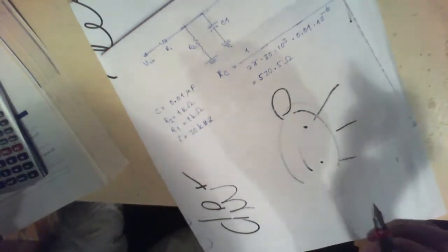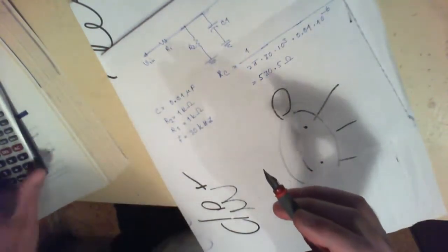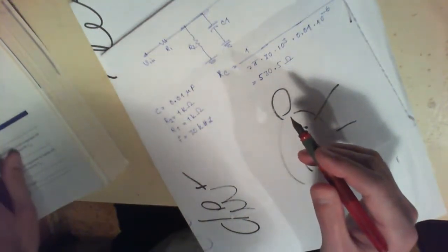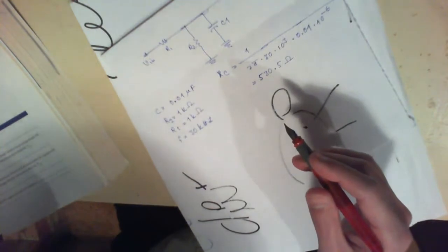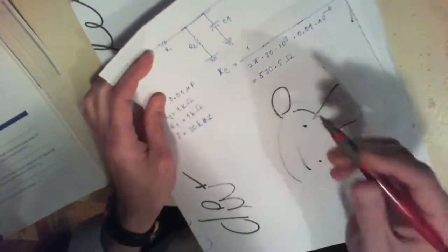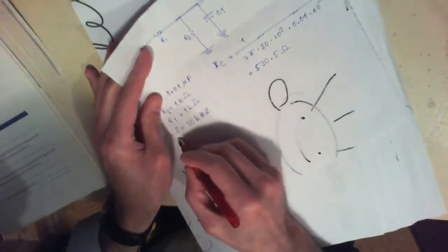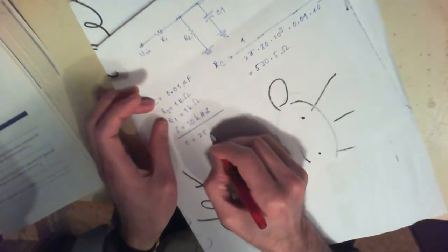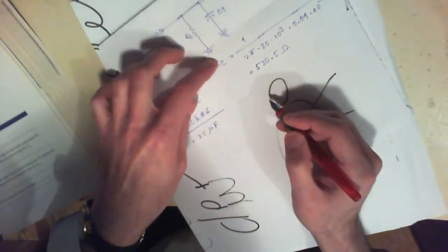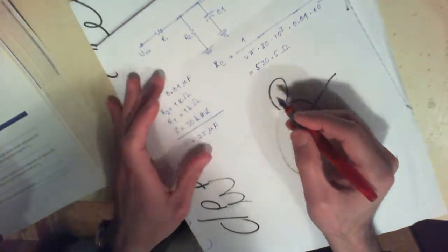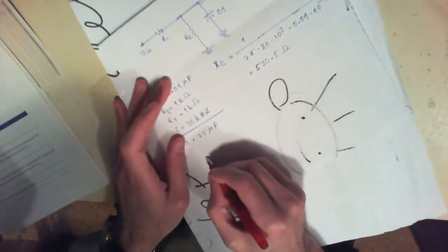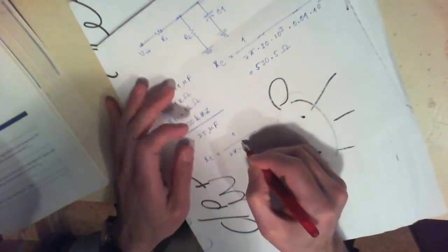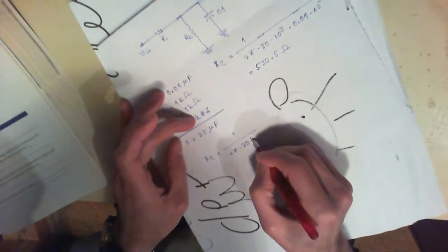an actual experiment. So for example, if you go for a capacitor with some value like 25 microfarad, if I swap this capacitor with a capacitor that is 25 microfarad, and then keep this resistor as 1 kilo ohm as it is, then my X of C is going to be 1 over 2 pi times F, which is 30 kilohertz.